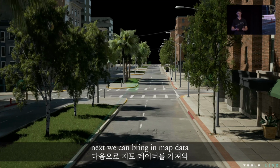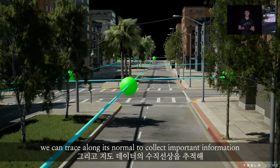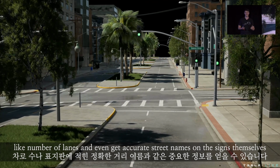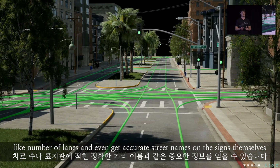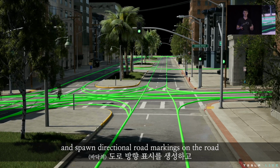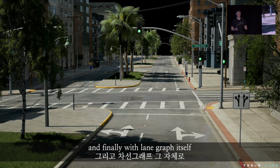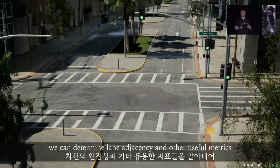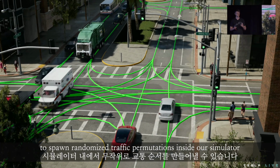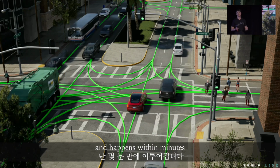Next, we can bring in map data to inform positions of things like traffic lights or stop signs. We can trace along its normal to collect important information like number of lanes and even get accurate street names on the signs themselves. Next, using lane graph, we can determine lane connectivity and spawn directional road markings on the road and their accompanying road signs. And finally, with lane graph itself, we can determine lane adjacency and other useful metrics to spawn randomized traffic permutations inside our simulator. And again, this is all automatic, no artists in the loop, and happens within minutes.